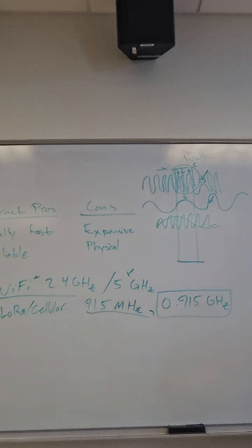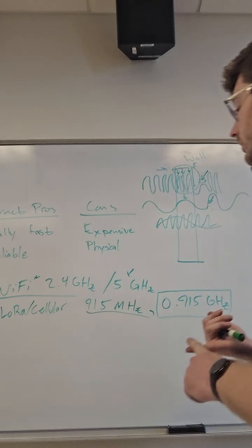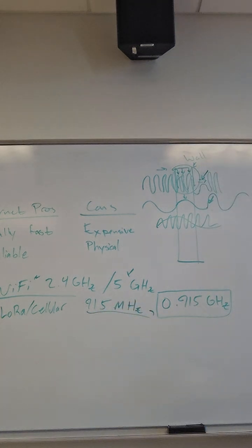So if you are in the same room as your sensor or your gateway, it's much better for 5 gigahertz than if you wanted to talk to a device that was across the compound, in a different room entirely, all the way over here, because it would have to travel through many walls and concrete and all that kind of stuff. Okay, so different radio frequencies, different radio protocols can also affect this, right?